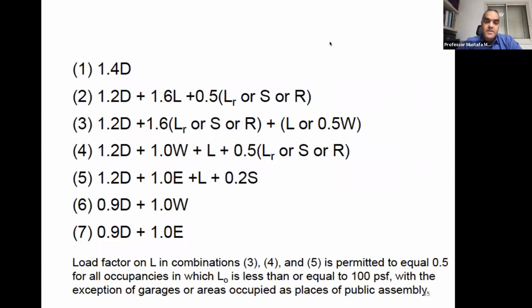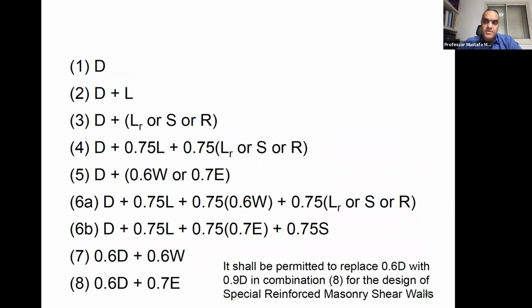Now, for the design, masonry can be designed using strength design similar to concrete, and for those we need to use factored loads. Again, this is similar to concrete. Or if we are designing using ASD, allowable stress design, or working stress design as it's referred to in some of the documents, we have to use unfactored loads, or this set of load combinations, which are listed in IBC and in ASCE 7.